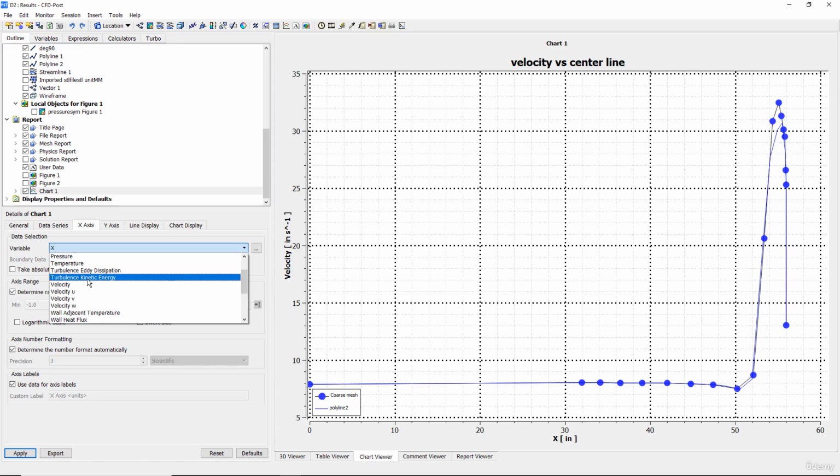So based on the mesh count they are different, but once you normalize them on the x-axis, they have somewhat different values here. So my recommendation is that whenever you want to take the values, you should always check how different variables behave by plotting data at different locations, and what the physical significance of these variables is on your results.